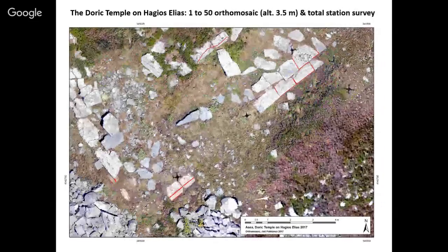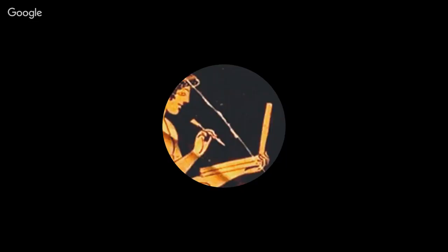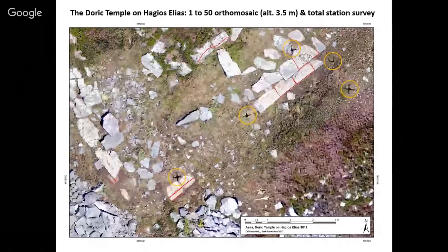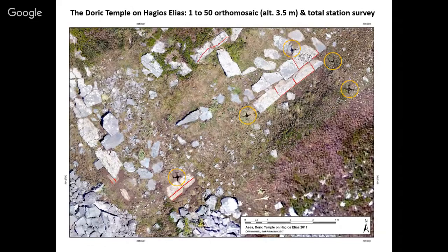One thing I wasn't thinking about is that we were there at midsummer 2017, and when I was running the final model of the site at 3.5 meters, the sun is exactly overhead, and when you're running the shots vertically down, the drone's shadow appears in almost every single picture. You can get rid of it in processing, but that was a bit of a surprise.